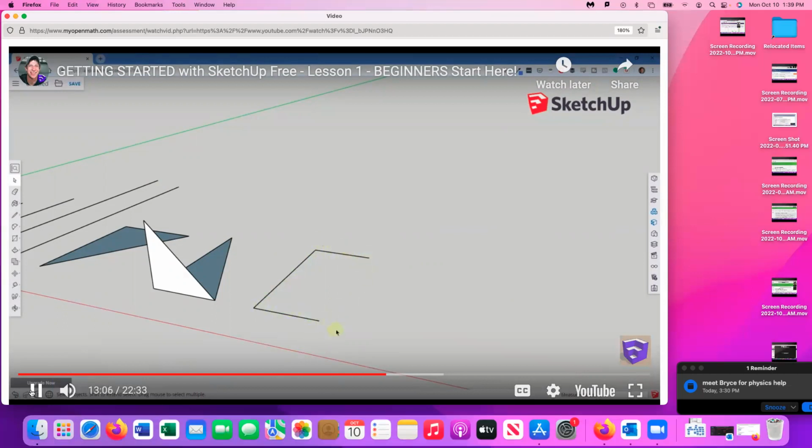And so if we wanted to get that face back, all we would have to do is just redraw across this edge. So you can see how I just drew a line from here to here, and that allowed me to heal this face inside of SketchUp.